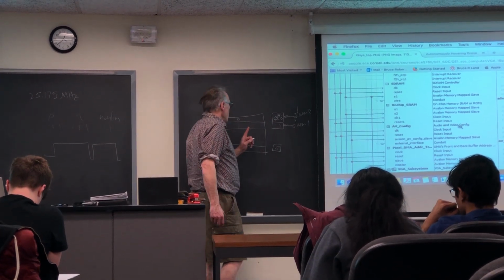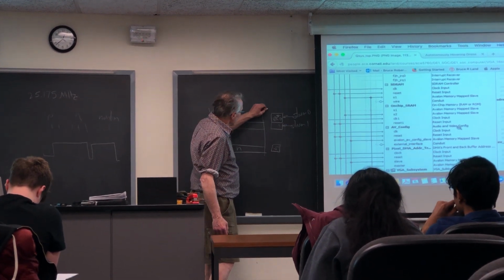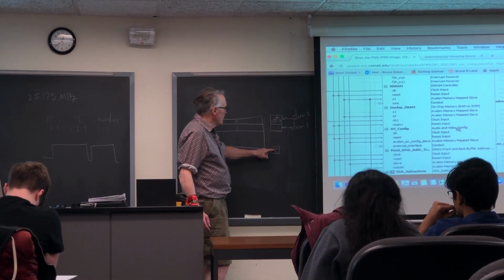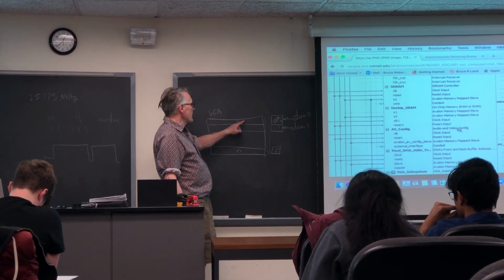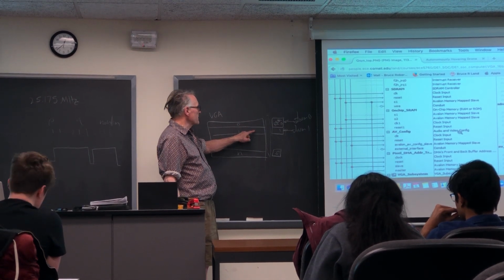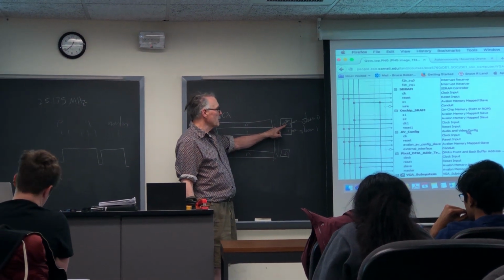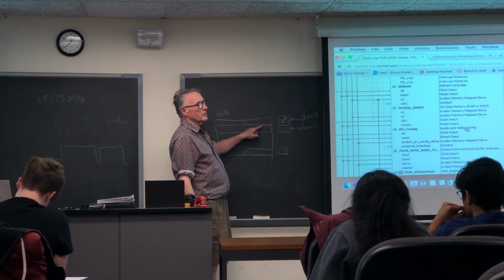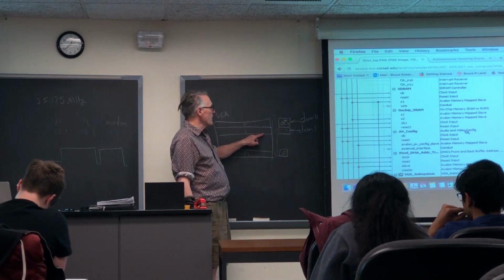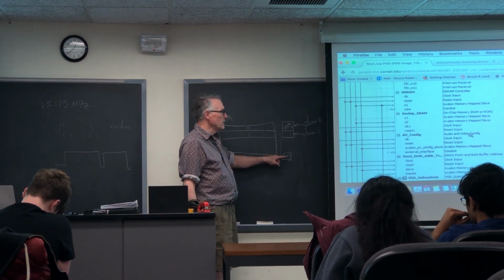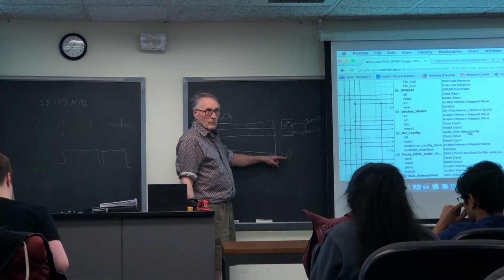Then the VGA controller is going to mux the output of these RAMs to decide what color pixel to draw in each section. As long as you're in the top section of the screen, it'll read from RAM 0. When you go into the second stripe, it reads from RAM 1. From the nth stripe, it reads from block n.